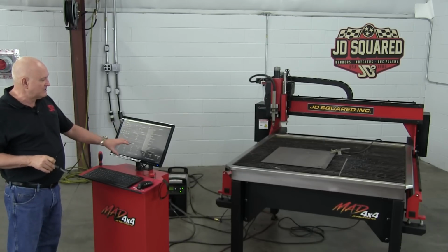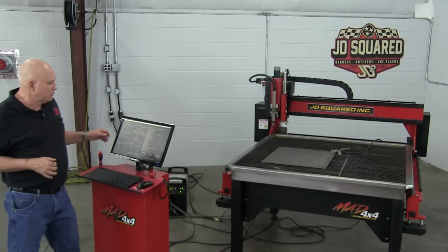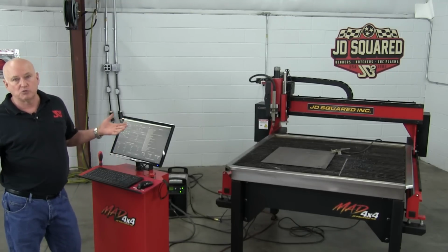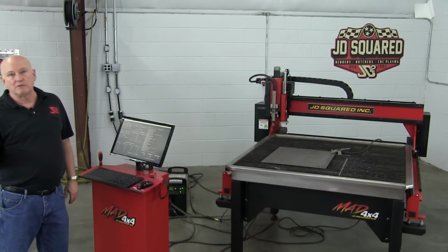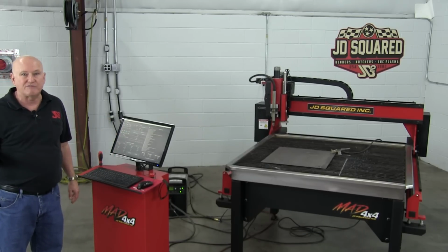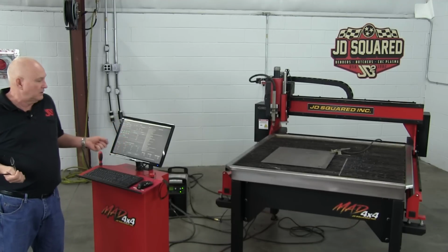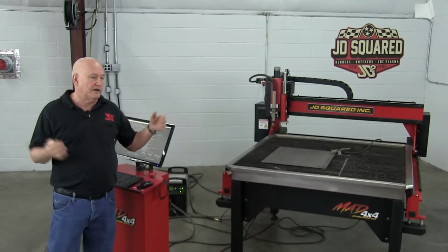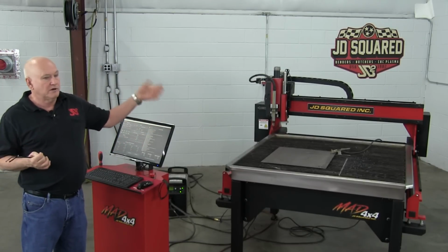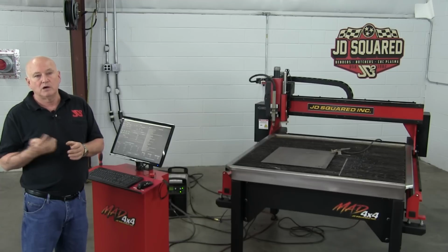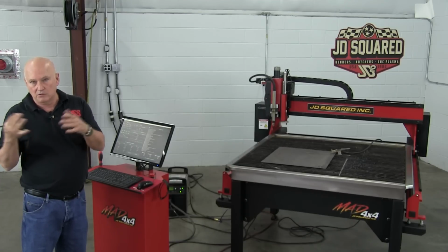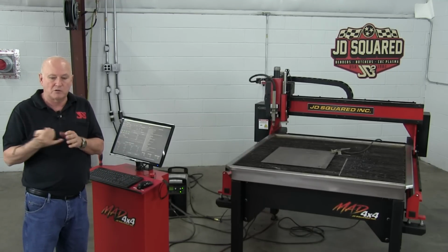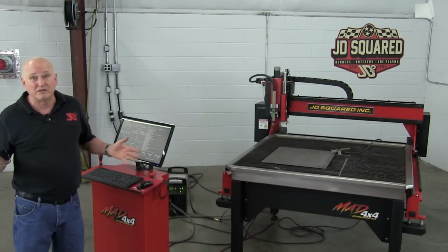Another thing we've done by setting all the kerfs and everything here is we are working on add-ins to our program, standard shape add-ins. For instance, I want to cut a 12-inch circle, right? Does it really matter if I'm cutting that 12-inch circle out of 16 gauge or half-inch metal? I just want a program to cut a 12-inch circle. Well, currently, every machine that we've seen, until you get to the really high-dollar machines, and I'm talking six-figure machines, you've got to create a new CAM program. What have you changed? You've changed the kerf width, because you're going from thin to heavy. You've got a heavier kerf, so you move the offset lines a little bit further out, and you've changed your voltage and amps. That's really all you changed.